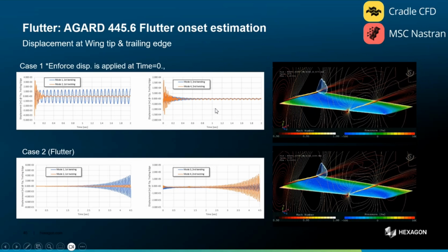But in some cases, what you want to avoid is the fluttering effect. With the fluttering effect, you get an initial solicitation, and then along the time, this solicitation will be amplified. That's the same story as the video of this bridge that was dancing. So this is definitely not what you were targeting in terms of application, but physics are what they are. And sometimes you also get some fluttering phenomenon. So you need to be able to anticipate them, and you need to be able to catch them through simulation.